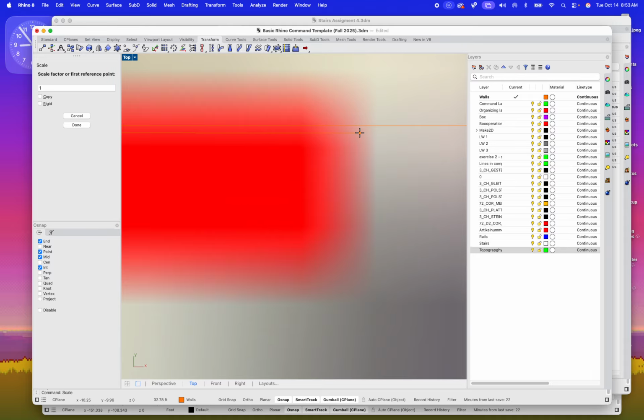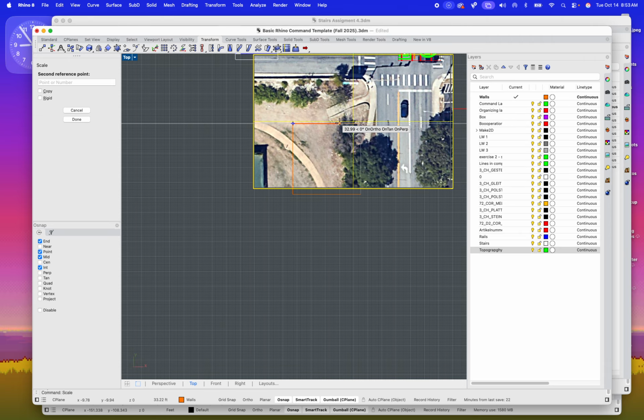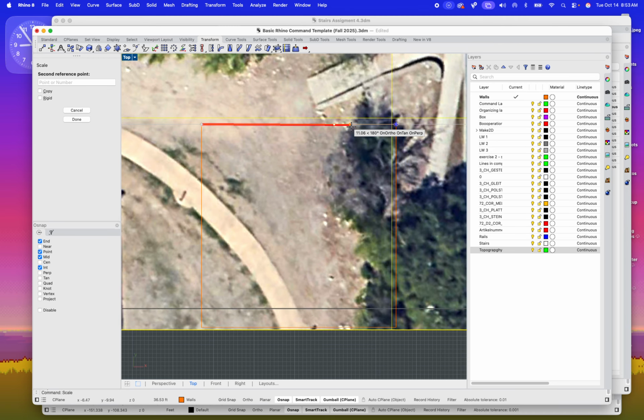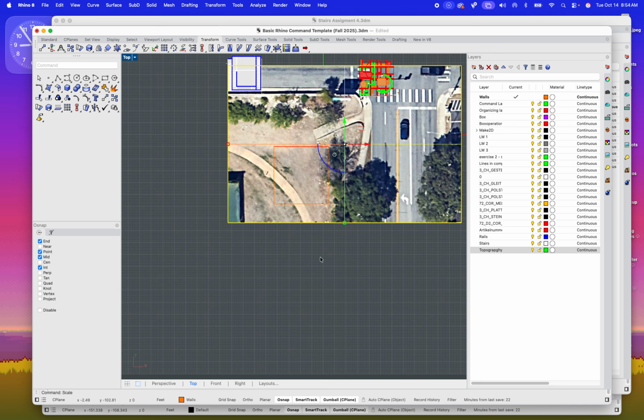Don't get me wrong, it's inaccurate down to the pixel, so usually I just pick somewhere pretty close. You can kind of see that there's a very red spot usually, and the end kind of fuzzed out. Again, I usually just pick the middle. To be fair, we're at a very microscopic scale now. So zooming out, now it's going to ask, hey, where do you want that 48-foot line to be? Well, I want it to match with 48 feet. Voila, just like that, I have a scaled model that fits perfectly.